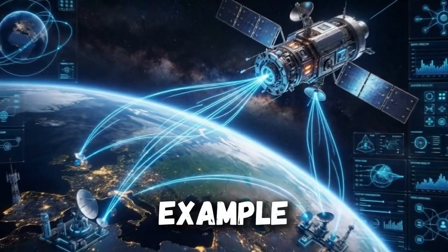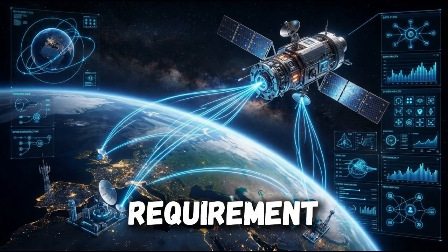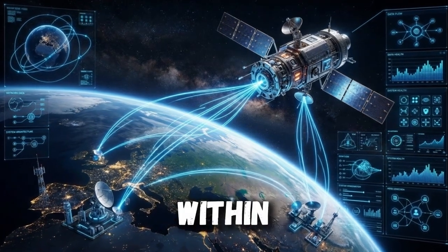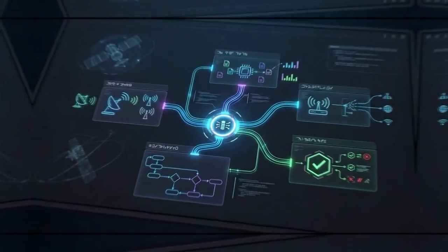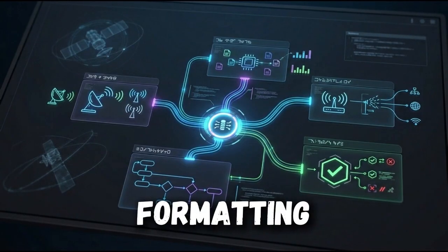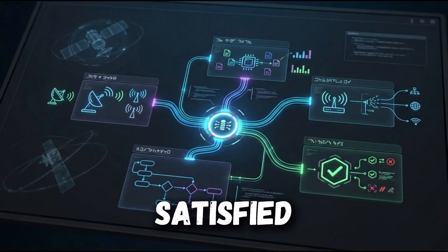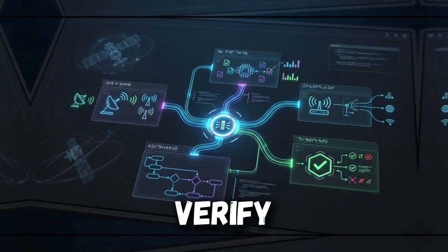5. Practical examples, satellite telemetry. Let's use the telemetry example from the last video. Stakeholder intent, well-written requirement. The satellite shall transmit telemetry to ground stations within 2 seconds under nominal conditions. In the model, this requirement derives 3 child requirements: data formatting, antenna pointing, and transmitter power. Each child is satisfied by specific blocks and behaviors. Dedicated test cases verify them.